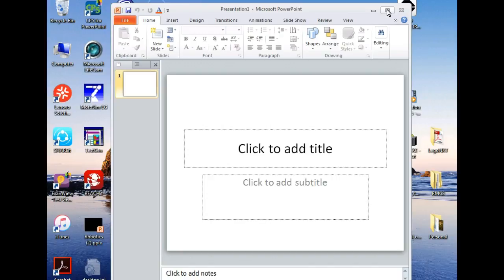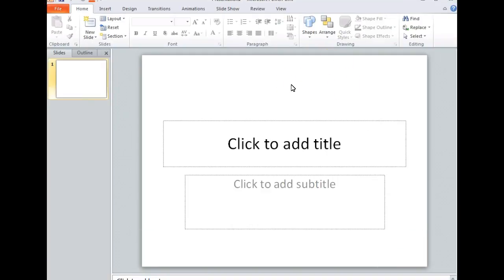All of them support at least 3 move instructions. Now, when we're talking about move instructions, we're not talking about jogging, right? We're talking about writing programs. Does everybody understand that? I've seen on the test that some of y'all don't understand the difference between jogging the robot and a move instruction. When we jog the robot, we're manually moving the robot to position that end of arm tool, right?